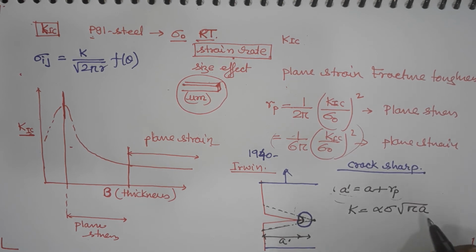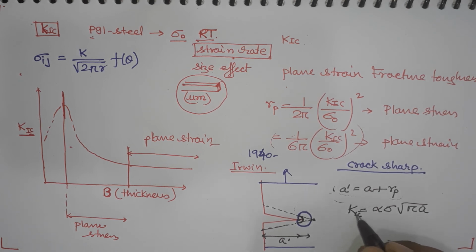and then there is some plastic deformation. So, then you can put this value. You have applied some amount of stress, you had some amount of a, then the rest of the things are known to you. So, you can calculate K1C. Okay.